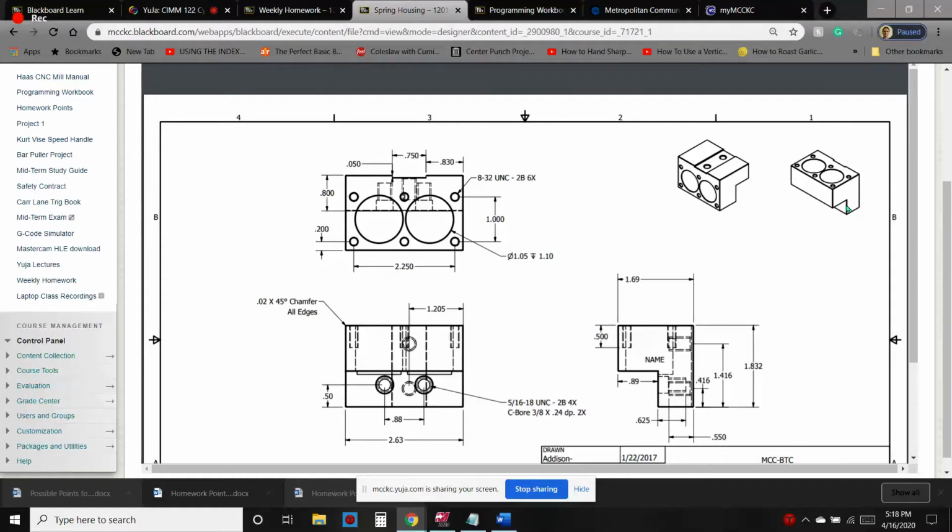And so what we end up doing is on our 3rd operation, when we mill this slot, drill the 2 holes and tap the holes, we also come through with the end mill and try to carefully blend this little bit of material in with the rest of it that's been milled, if that makes sense, because there will be a line right here on both sides where there's just a little bit of material left. Okay, so that's how we do it in 3 ops.